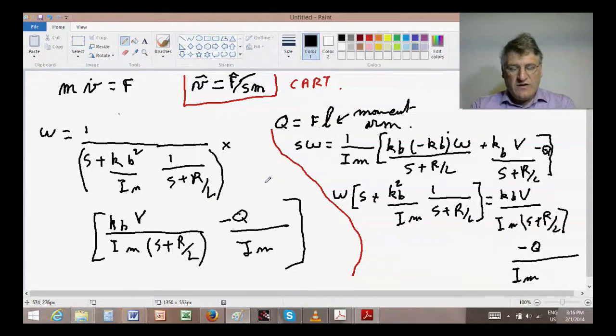The way to simplify this equation is to go back to the equation on intensities and to say that intensities establish themselves to steady state faster than the motor can reach its mechanical steady state, that is, rotates at constant speed.